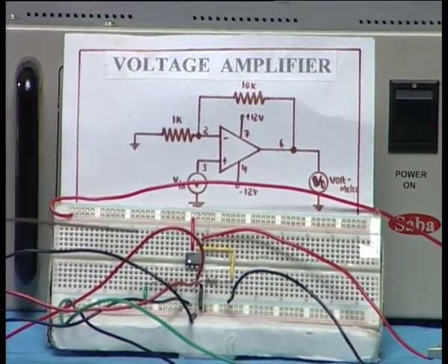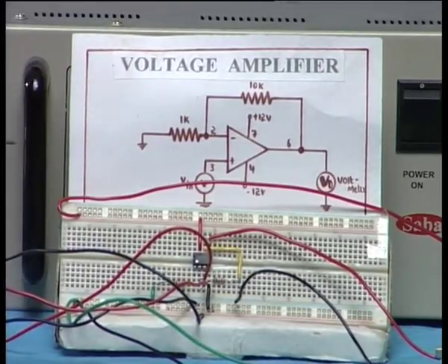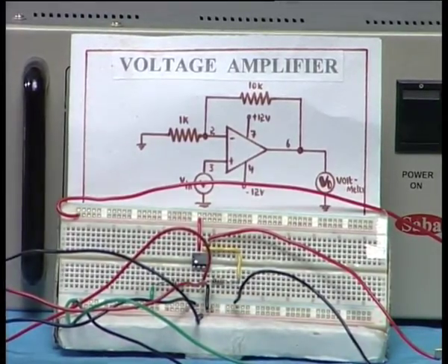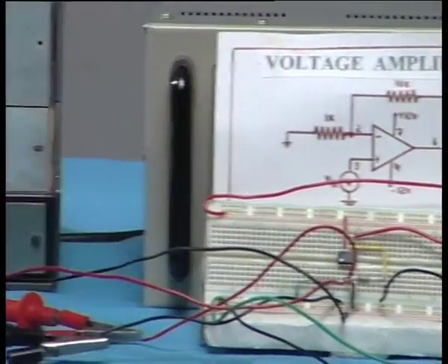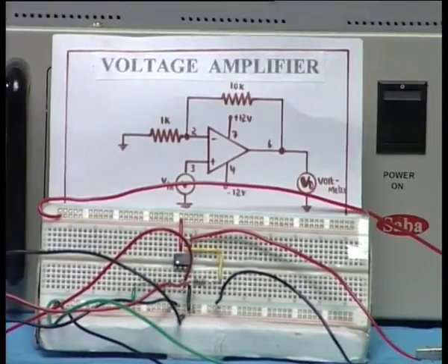There is always a tolerance band, that means the resistance need not be precisely 1K and 10K, it can be within plus or minus 10% of those values, and that tolerance variation is the reason for the slightly different voltage that you get at the output. If I choose 1% or 0.1% resistors and put them in the circuit, you would find it will be an exact multiplication of 11.